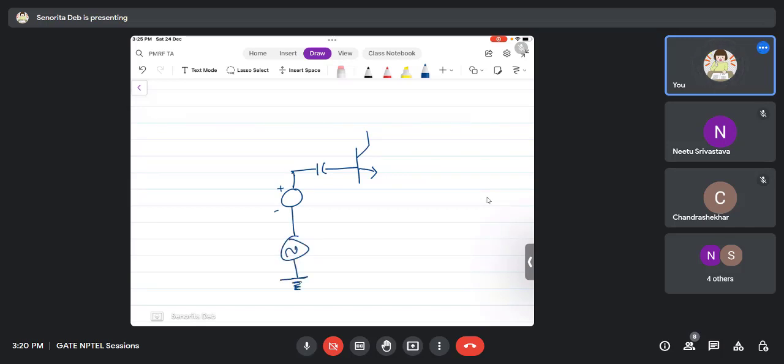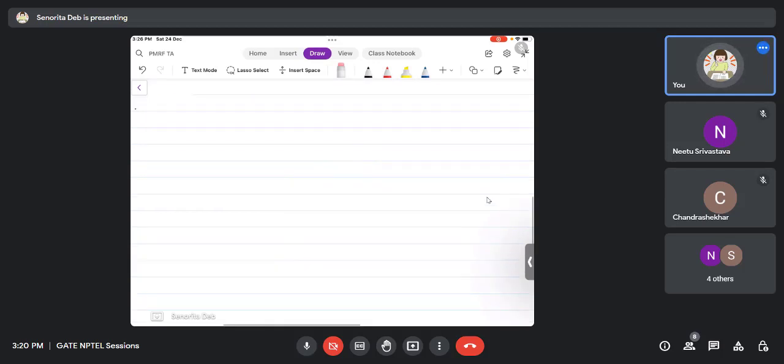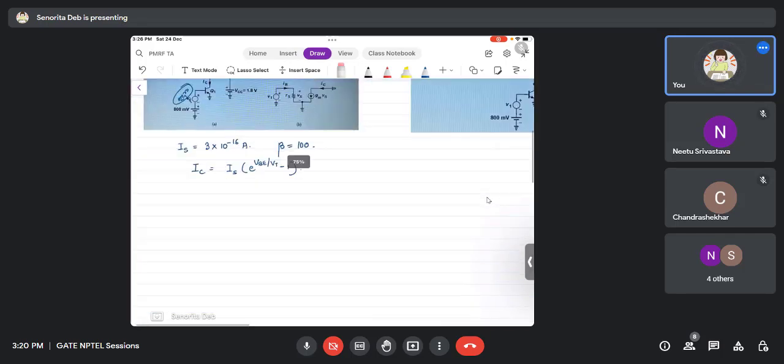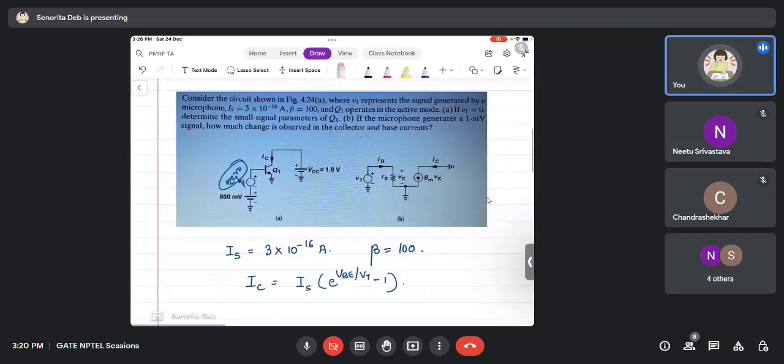sure that if the frequency is 0, the AC signal cannot perturb here, but the DC will be able to bias it. So normally we use DC coupling capacitors to make sure that the circuit is biased, and after that when we put a frequency, that signal appears along with the DC signal, so that both of them are not disturbed. The transistor is biased, and at the same time the analog signal is put.